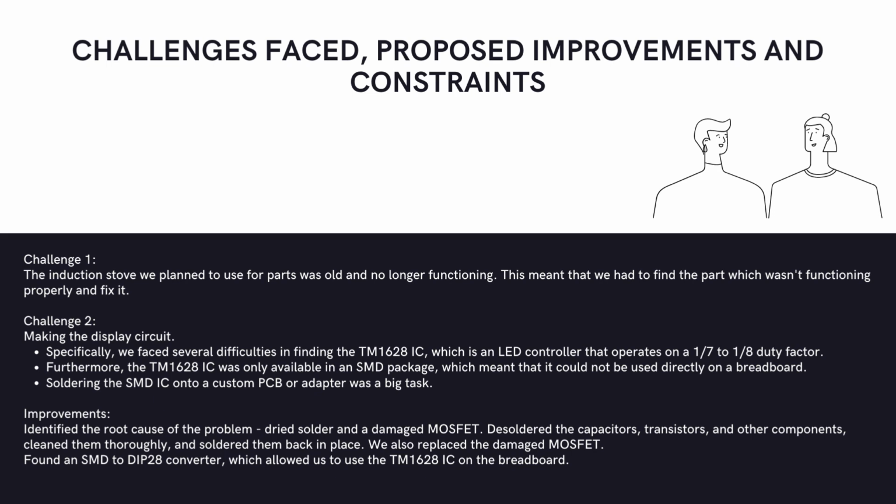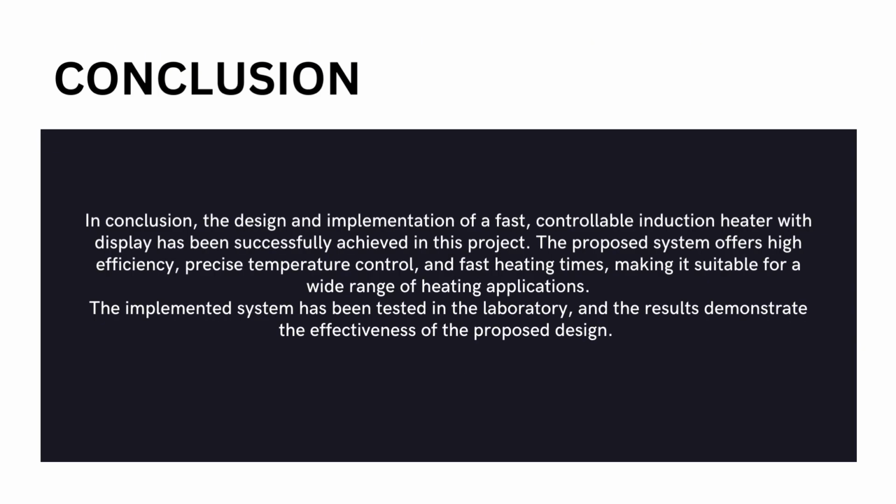So for improvements, we identified the root cause: damaged MOSFET and dried solder. We fixed it, and we got our circuit to work. In conclusion, the design and implementation of a fast controllable induction heater with display has been successfully achieved in this project.